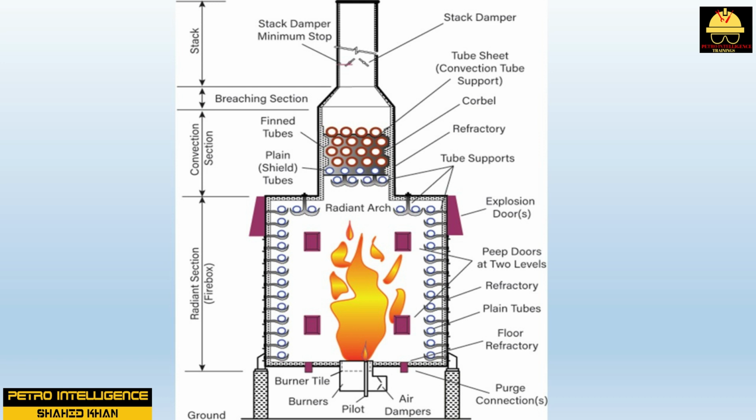A color chart of steel tubes shows 10 tube color variations associated with temperature. Process technicians visually inspect these tubes and compare them to the color chart. Convection tubes are located in the roof of the furnace and are not in direct contact with burner flames. Hot gases transfer heat through the metal tubes and into the charge. Convection tubes usually are horizontal and are equipped with fins to increase efficiency.